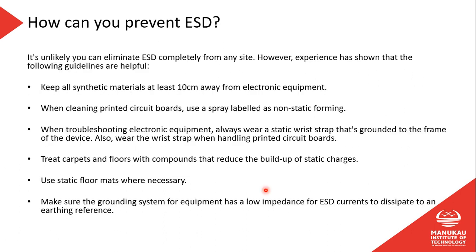How can we prevent it? Keep all synthetic material at least 10 centimeters away from our electronic equipment. When cleaning printed circuit boards, use a spray labeled as non-static. Always wear a wrist strap if you're touching electronic equipment, if you're opening electronic equipment and touching the boards. Treat carpets and floors with compounds that reduce the buildup of static charges. Use static floor mats, and make sure the grounding system for equipment has a low impedance for electrostatic currents to dissipate to an earth reference.